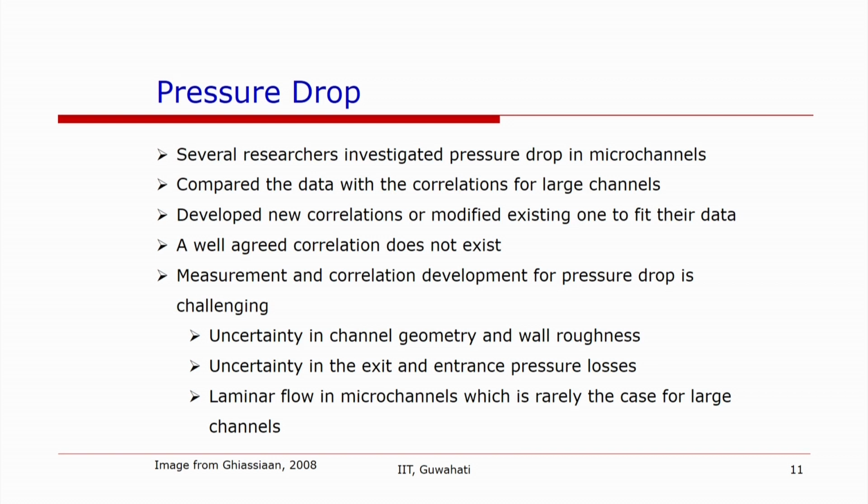So now let us come back to pressure drop in microchannels, which has been investigated by several researchers in the past 20-30 years, and many of them have compared the data with the correlations for large channels, and most of them had only limited success. So the correlations have been modified to fit the data, and rarely is there a well agreed correlation, as with void fraction. The same is the case for pressure drop, and there are a number of uncertainties for pressure drop.